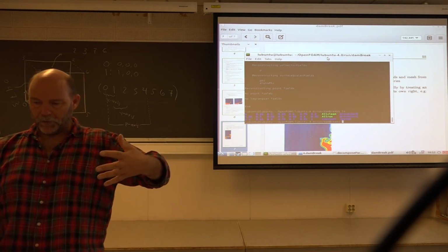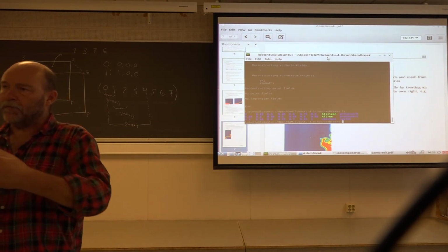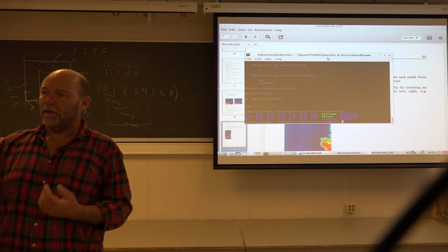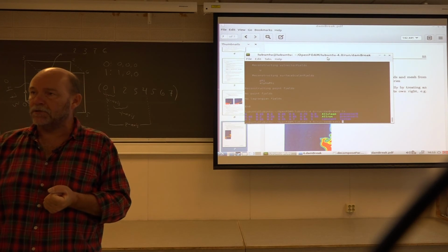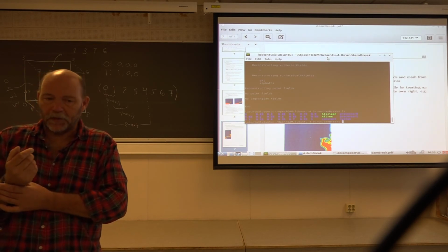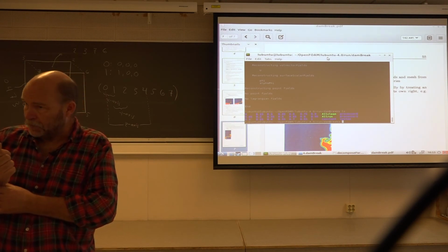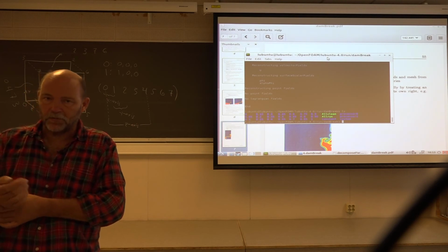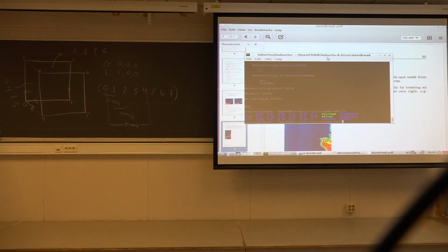Then of course, if something flows out of the one calculation, it enters into the other one. So this information has to be exchanged, they have to talk to each other during the entire simulation. So you have some overhead. So of course it doesn't scale perfectly, but OpenFOAM has been programmed very well, so it scales quite good. So with 2 processors, you don't halve the CPU time, but, well, we can try it. It was 4.7 seconds.